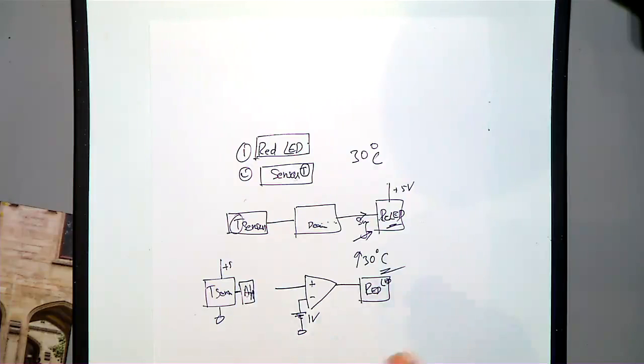If you find a lot of noise, obviously, if noise is there, you will be adding one more block, a filter. If there is no noise, you don't need a filter. So with the temperature sensor, you are getting some voltage. Most of the time with a sensor, you need an amplifier, because the voltage detected is small. Then you amplify accordingly, and then you have to test it.